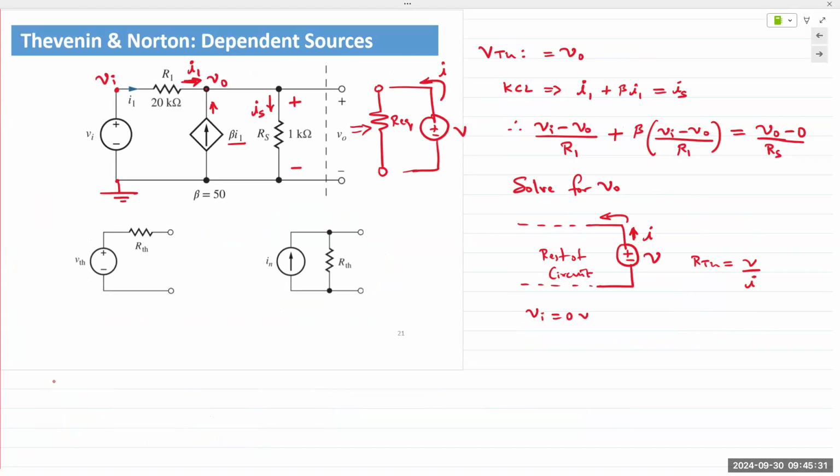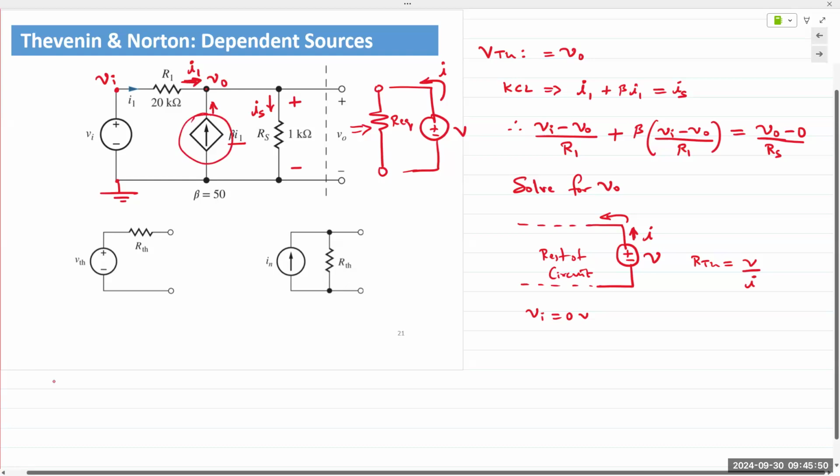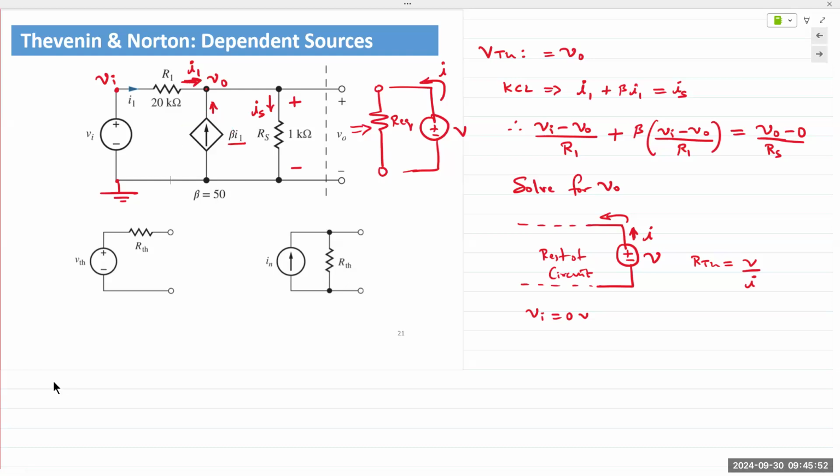And then the other reason is, of course, if you want to find Thevenin resistance, it's easy. You just find Req. Sometimes we are not able to reduce all circuits to a single resistance to find Req. Or we may have dependent sources in the circuit like this one, which cannot be reduced to 0.